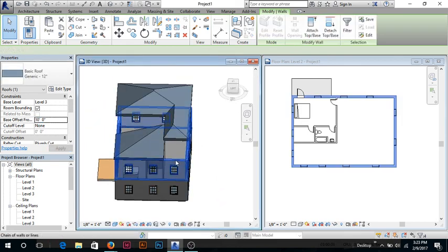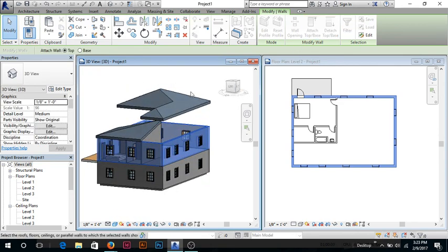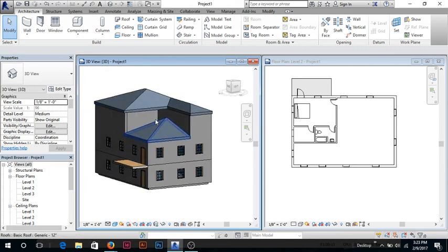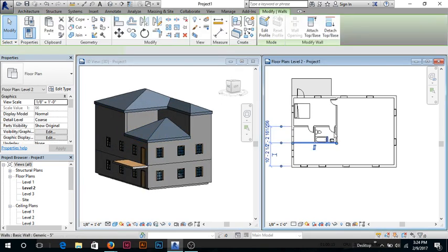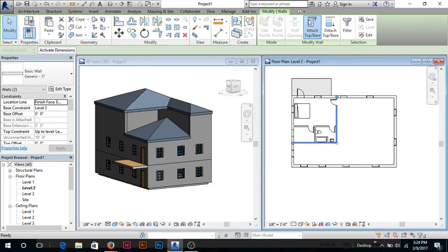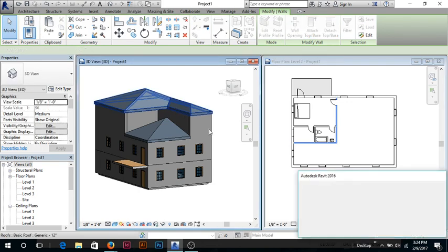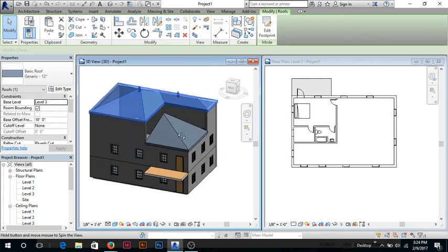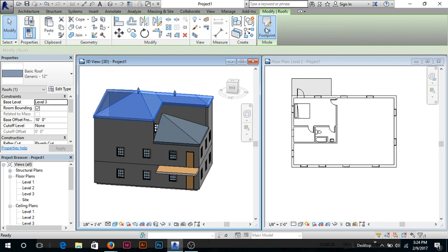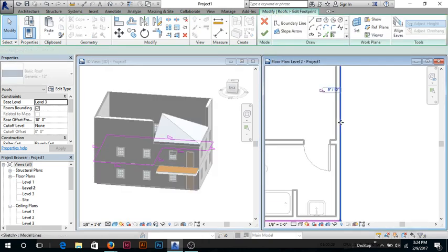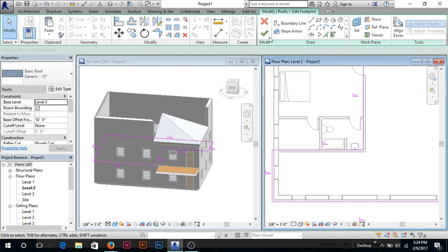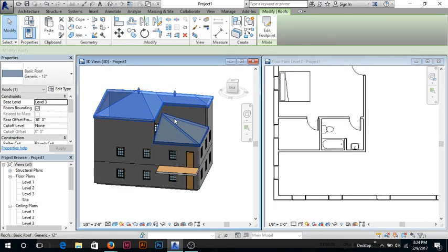I can extend these walls, attach to the top of this, and then we can draw more walls here, or extend these walls up, attach. Whoops, okay, that doesn't work. But either way, that's basically how you do things. If I added this roof to a line on top of these walls, then once we attach to the top, it's going to recognize that, okay, it aligns with it.